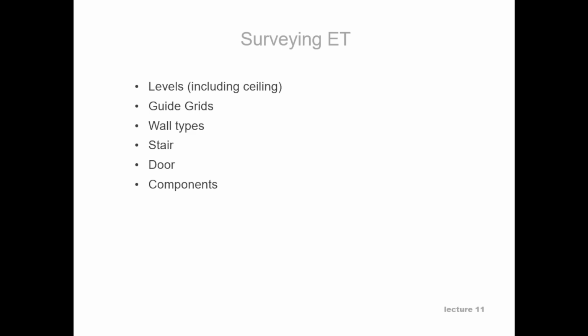You also need to note the wall types. Is this gypsum wallboard, GWB, or drywall? Is it brick? Is it CMU, concrete masonry unit? We want to note all of those items and take the measurement, if we can through a jamb, of the thickness of the wall types.